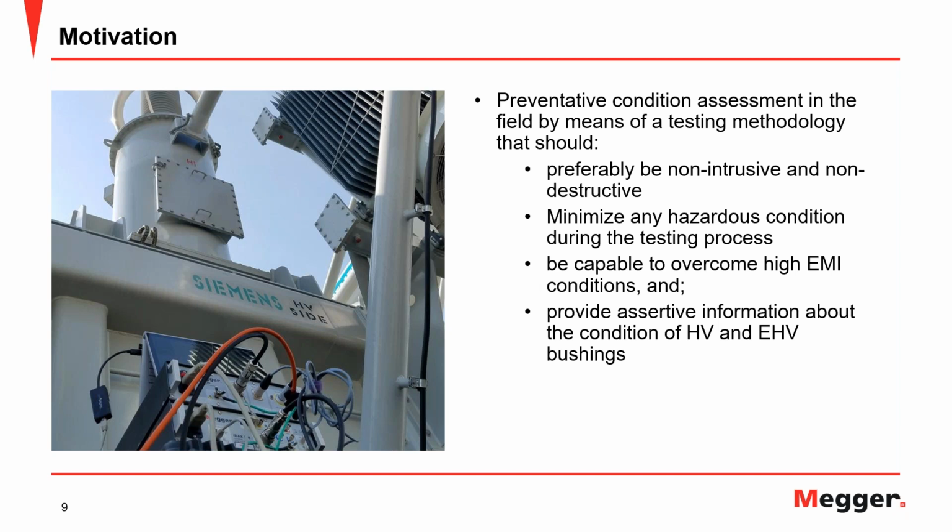What kind of actions can we take to improve the quality or to avoid damage of major equipment that is related to these bushings? So what are we trying to look at? If you look at the bushing, it has no sensor added to it, right? The only type of sensoring that you may see in the bushing by construction is only the liquid level gauge, right? You can see probably what the level of oil is inside the bushing, but that's all you can see. There's no other instrumentation mounted.